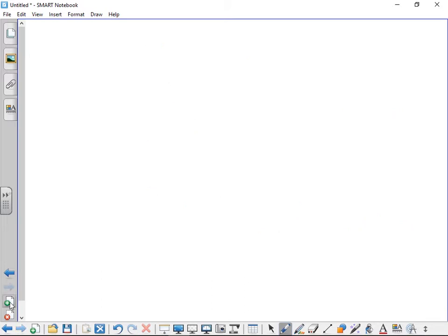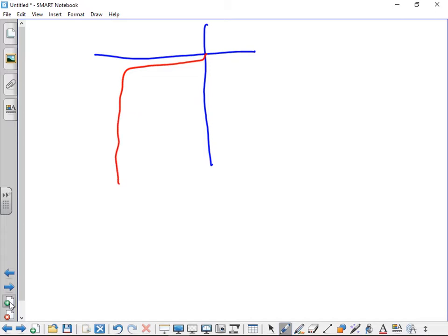So if we look at how that works, and going back to that graph again, here we have our graph. Like I said, this one over here is IZK, and over here we have IZM, but this one here is IZT, which is our operational current inside the Zener diode when there is no change at all.